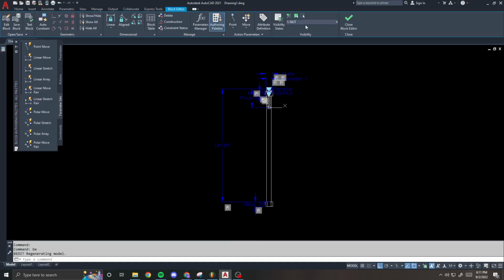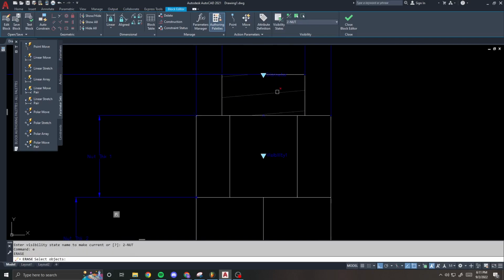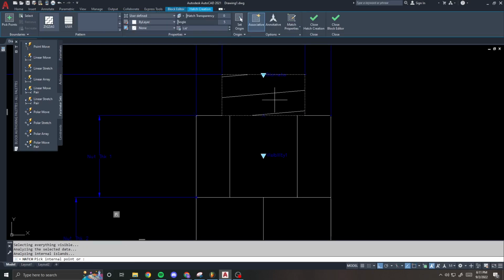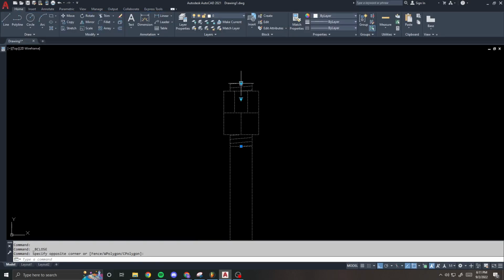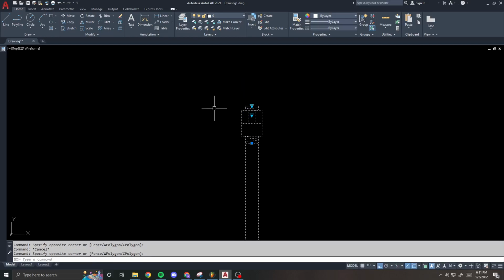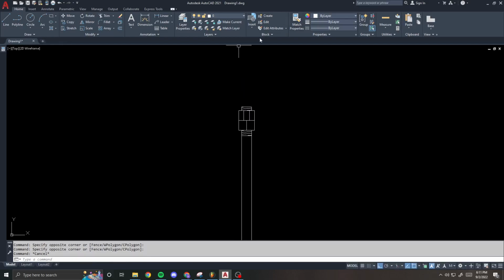Now the 2-nut doesn't like what I just did, so I'm gonna rehatch the 2-nut. Close it, save it. And I'm moving super fast. I'm fixing things. Whenever you mess with a hatch boundary, it kind of destroys the hatch. So you have to reset the hatch boundary and rehatch it. Let's make sure I didn't mess things up with my projection. And I bet you I did.